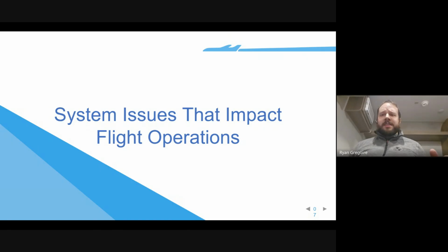Or some other system on the aircraft that might impact some procedure the pilots have, but wouldn't really impact us dispatching. Like, for instance, if the first officer's flight director was inoperative, the procedure might be ensure that the captain's flight director works. If it does, that's the full stop of what we would need to worry about. There would really be no major impact on us.